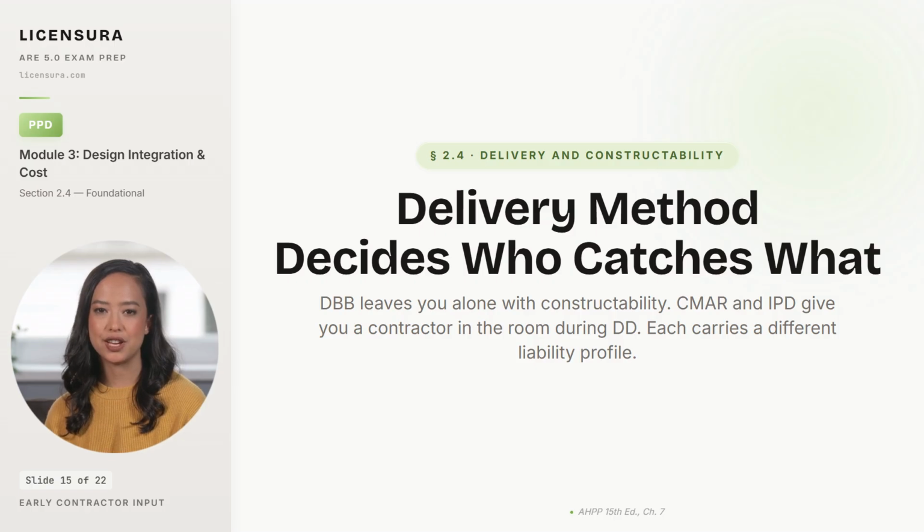Here is the delivery method rule that drives constructability outcomes, and you must hold it straight on the exam. The moment the contractor enters the project is the moment field experience enters the design, and that moment is set by the delivery method the owner chose. In design, bid, build, the contractor is not selected until the documents are complete, which means the architect carries the constructability burden alone through every phase.